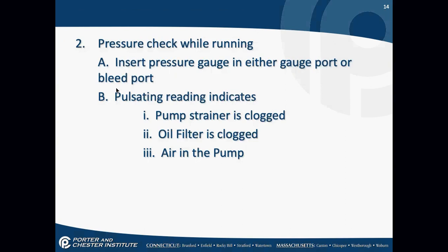It means that there's a pump strainer that's clogged, or the oil filter on the tank is clogged, or there's air in the pump. Bleed it out. So pulsating readings on a pressure gauge while the system is running is one of these 3 items.